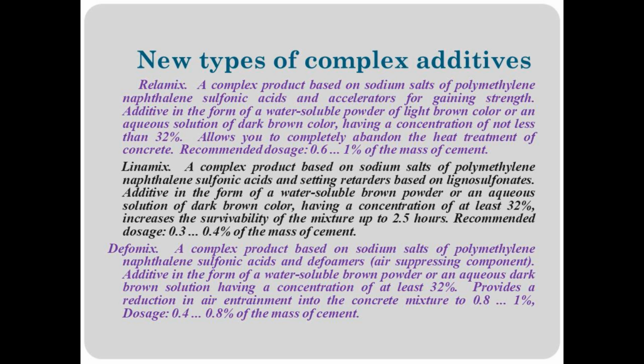Additive in the form of a water-soluble powder of light brown color or an aqueous solution of dark brown color, having a concentration of not less than 32%. Allows you to completely abandon the heat treatment of concrete.